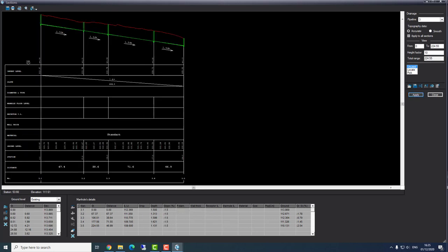Okay, great. Now again, we will insert the diameter. Here for the drainage pipeline, I'll insert 500 millimeters. And now we see how it looks. Now I'll define the size of the manhole. This time I won't use the automatic option.